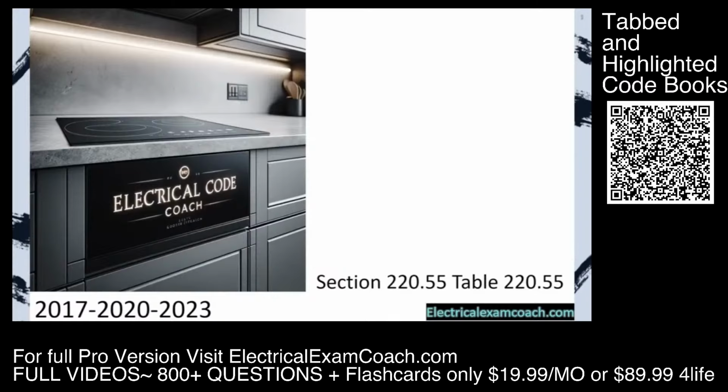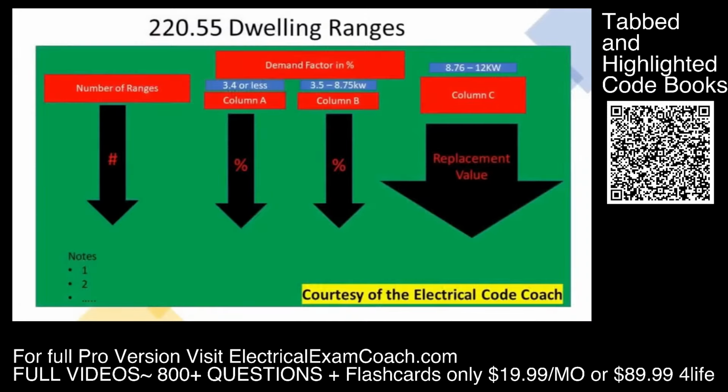Let's get to it. When we get to table 220.55, we're going to read the black bold heading at the top of the table to make sure that we're in the right table. Then, starting on the left-hand side, we're going to find our number of ranges: 1, 2, 3, 4, 5, and so on and so forth. Then we're going to notice that there are 3 different columns. They're really in 2 different groups. Column A and column B are grouped together under the demand factor in percentage column. And the reason that's so important for us to watch out is because column A and column B are multipliers. They're actual demand factors, but column C is a replacement value, and you'll understand more of what that means as we get farther through this video.